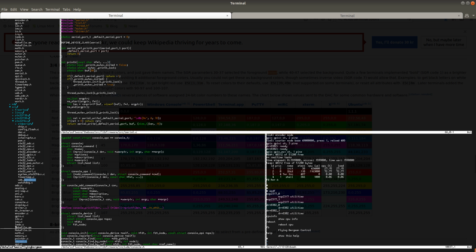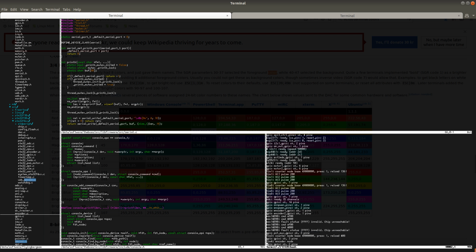And then I can go to this driver for the encoder, so MAX14890, which outputs here there's a fault status, so the chip is actually unreachable. These two chips have had problems with being reachable. I think that when I've been soldering them, there's probably some pins that didn't really solder properly. So let's see.